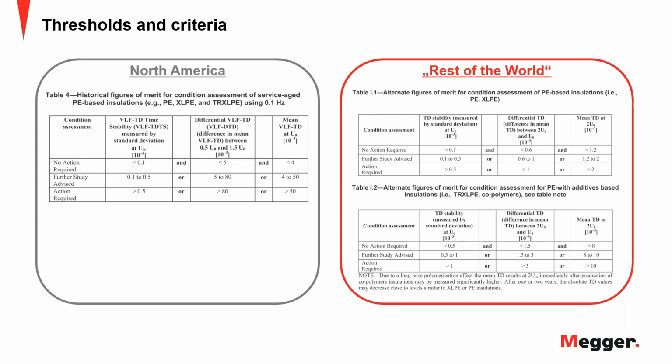And it sometimes goes even so far that on a splice, you need not just to say a splice, you need to know who makes that splice, because the materials are different from different manufacturers, and they have different, let's say, resistance to partial discharge. And so it becomes very, very tricky. Now, if you operate in your own system and you have enough data, then you can come up with some references and guidelines, but you need a lot of data.